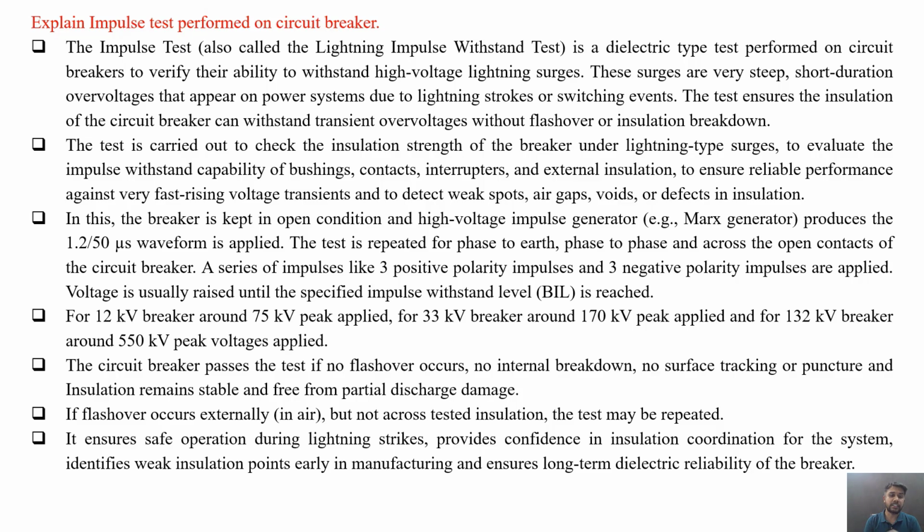If the flashover occurs externally, that is in the air but not across the tested insulation, the test may be repeated. It ensures safe operation during lightning strikes. It provides confidence in insulation coordination for the system, identifies weak insulation points early in the manufacturing stage, and ensures the long-term dielectric reliability of the circuit breaker. So this is all about the impulse test performed on the circuit breaker.